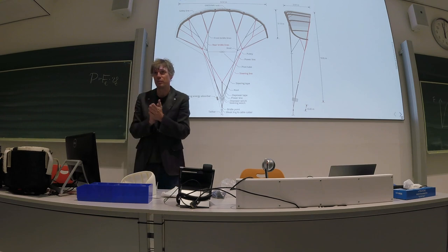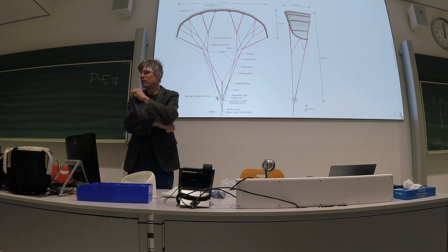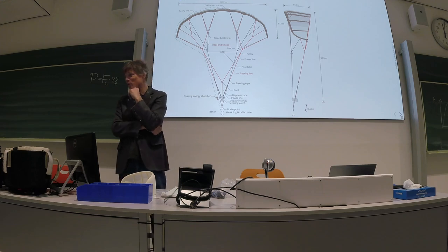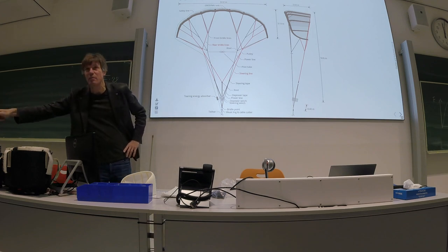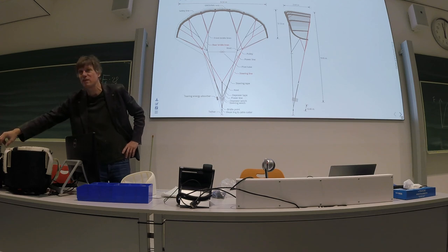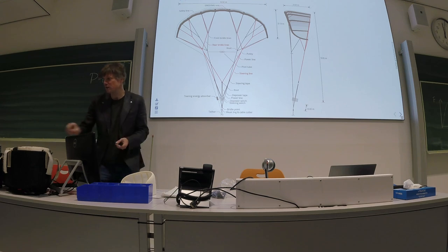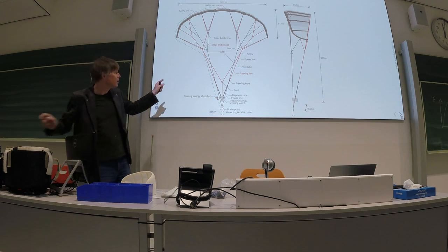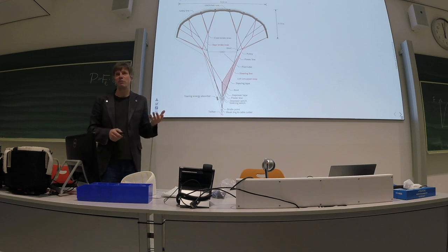Yes? Do you know how much torque those servo motors can produce? Now you're asking something that I would need to look up. I don't know this from the top of my head. But of course the high RPM motors, not a lot, but they run at 10,000 RPM, and then through this gearbox you get quite a strong pull. Oh, there's a gearbox? Yes, a planetary gearbox. And also these two pulleys, they increase the force by a factor of 2, right?